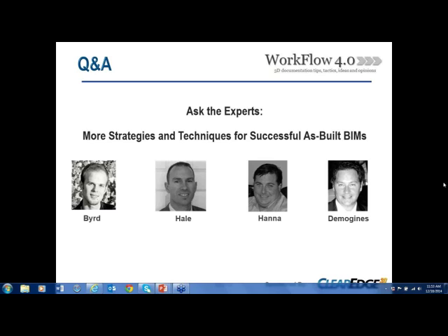They're all very happy with the 2 millimeter general accuracy that you talk about for the scan data, and then we tend to dial that back for specific modeling applications. So it might be 2 millimeters in metric terms. We might round that out to like an 1/8 inch in English terms, and then as we get down to the modeling accuracy, it's down to like a 1/4 inch or 1/2 inch. And pretty much everybody has been very happy with that.